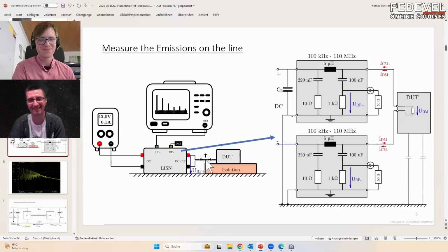Okay, I understand now. Yeah. So you can have on plus and minus RF compared to ground. And this compared to ground is now here on the output. And this is, let's say, the real test in the end. You are measuring one output here, which is the plus compared to ground, and then the other one. So then you switch here to 50 ohms and measure the other port. So RF plus is basically the plus voltage, and RF minus is the minus voltage.